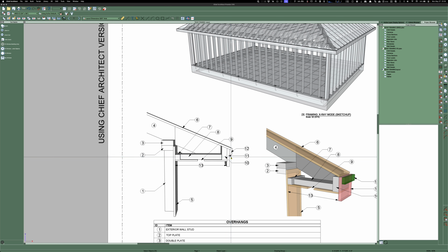Okay, what if somebody puts gutters on there? Now the gutter sticks out even farther. Do you go to the outside of gutters? I understand the point that if you're looking straight down from space, whatever's sticking out from your house the farthest would be considered the overhang. But that's not how it's framed. How it's framed is whatever the material is for the soffit, you make your subframing all match up to that.